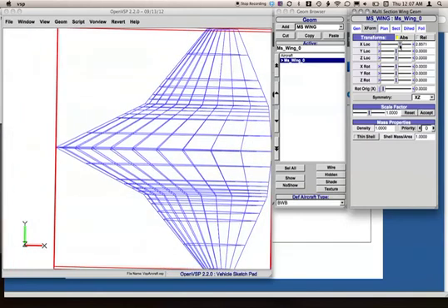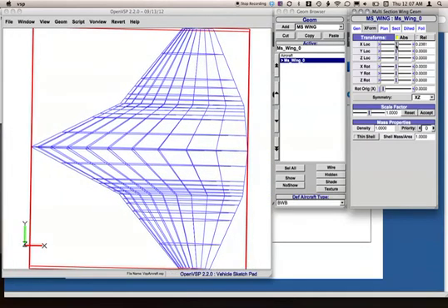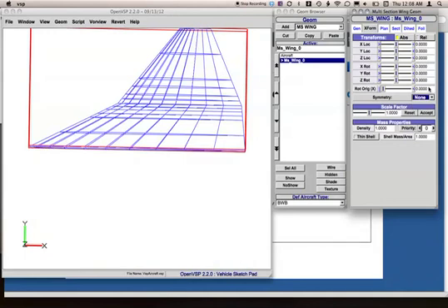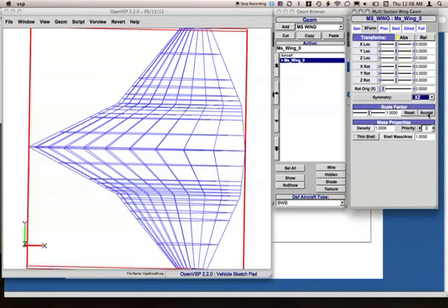Things like location, so that way you can anchor this to a specific point in your geometry, as well as rotation. Symmetry, how the symmetry is actually defined, which is going to be important, for example, when you want to define something such as a tail section. So, I have a vertical stabilizer, so I don't need any symmetry, for example.